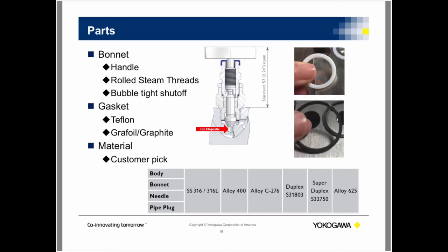Now your handle can also be allowed for anti-tamper. Sometimes technicians could be walking, they might hit a valve by accident. This allows you not to hit that valve, or just make sure that nobody touches the valve without permission. But in this case, this handle does not have the anti-tamper on it, and it's just a normal handle.